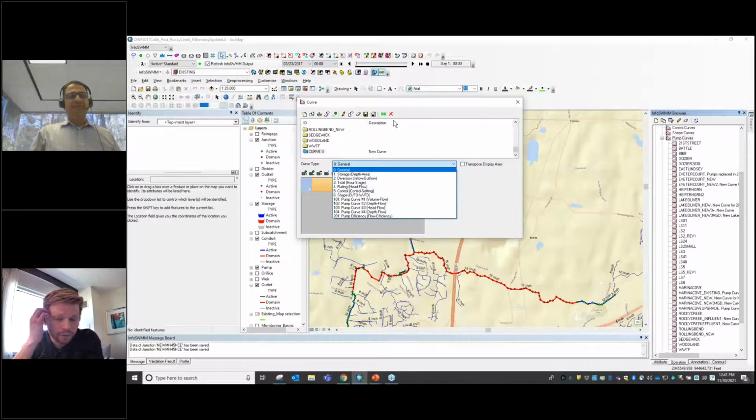Yeah, so Bob's saying the 102 pump is on depth and the 104 pump is a dynamic head, and that 104 is a more common pump type. But the head is what you will typically see. Typically the head is what you always see on the manufacturer's curve. It's the head against which the pump is operating, so total static plus whatever friction head loss, that will guide what your pump is pumping.